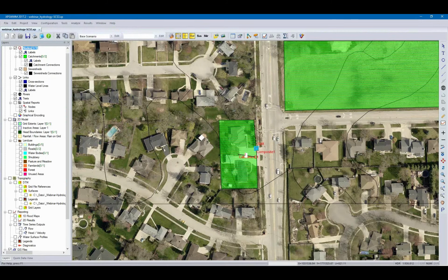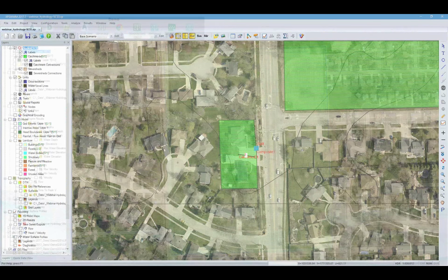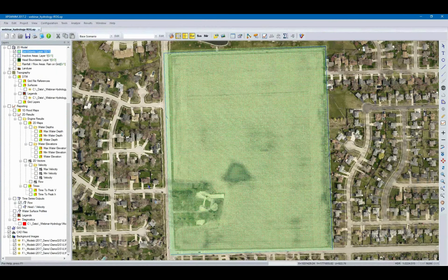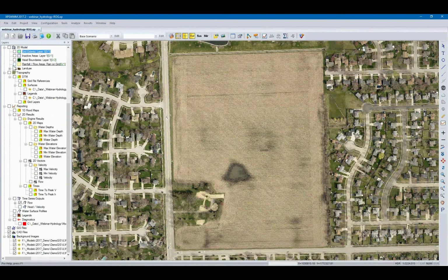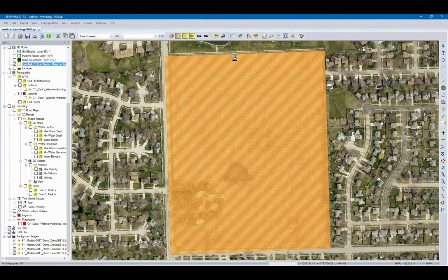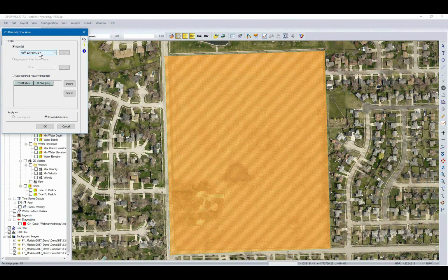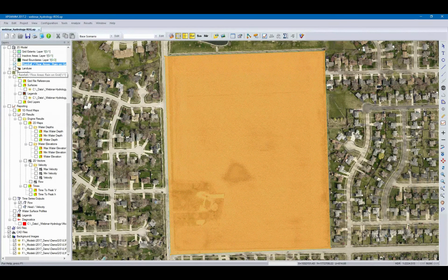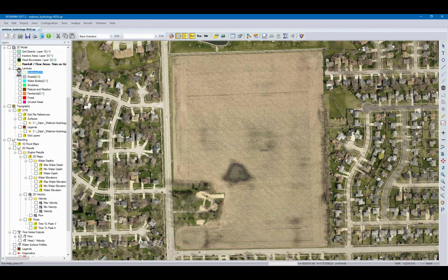Next, very quickly here, is rain on grid. Same model, same terrain, okay? But what I've done in this case is I've added a grid layer. I've also added that same rainfall, that 1 hour Huff first quartile distribution on that. I've also added the buildings. I've added the roads, okay? I've added this little bit of wetness, the water there. I've also then defined my farmland here.